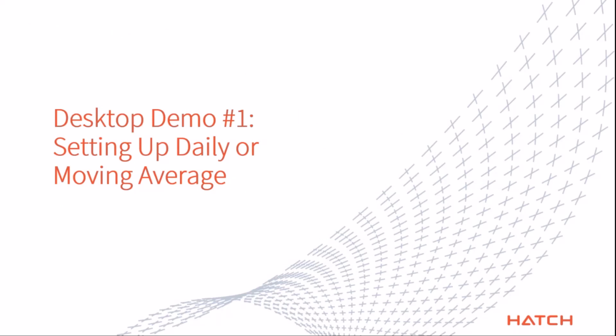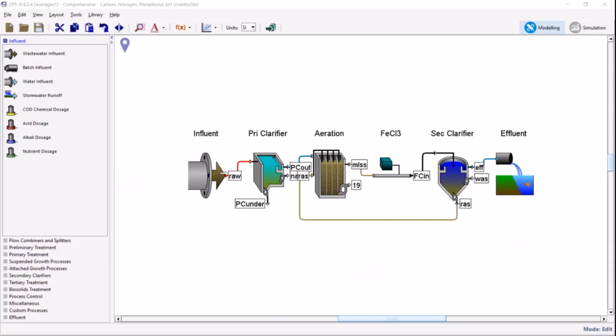Okay, so I'm going to start with something very simple, setting up a couple of averages here just so that you can get the feel for what it looks like. You can see here that this is a regular conventional activated sludge plant. This is obviously an influent coming in, a rectangular primary clarifier. We have a plug flow aeration tank, and all this is set up as an MLE system. So it's actually 3 tanks in series. The first one is anoxic. There's an internal recycle. So we're doing nitrification and denitrification, plus also chemical phosphorus removal here,